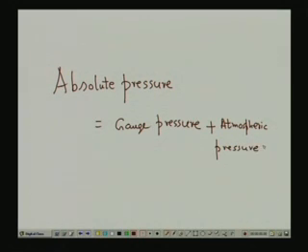Now, typically this U-tube manometer looks like the English letter U. That's the name that we have coined for it, U-tube manometer, and I should say it is one of the oldest pressure measuring devices that mankind has developed. Still it is used as a monitoring instrument in many process industries, or for estimating pressures in many places, starting from the bioreactors or the laminar hood or in the actual process. It has a wide range also.